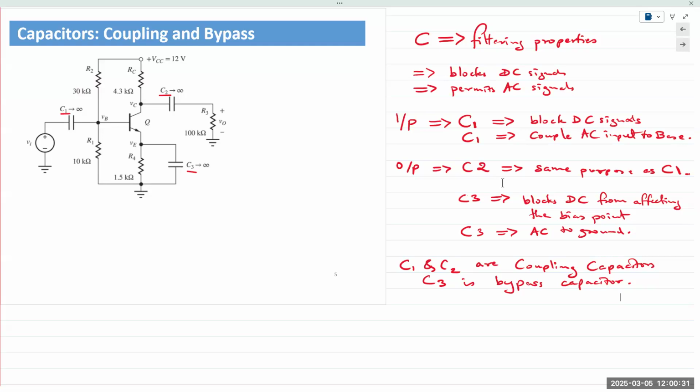Yes. The trade-off is using a connecting circuit at the output so that you can repurpose the design for multiple different input signals. Why not just use a clamper circuit at the output? Depends. If the capacitor does a good job, we don't need to do anything else. But if we get something in the output, then we would apply a clamper circuit. Clamper circuit was just an example. Okay, this is where a clamper circuit would be useful. One of the questions that students always ask is, when and why would we use a clamper circuit? This is an example where if you have a DC component in your AC signal, which is unwanted, then we add a clamper circuit to shift or remove the DC offset. But a capacitor would do the job well enough.